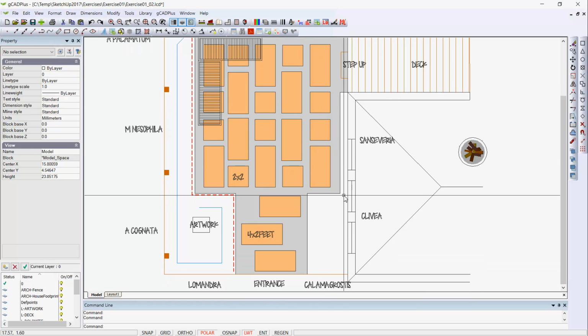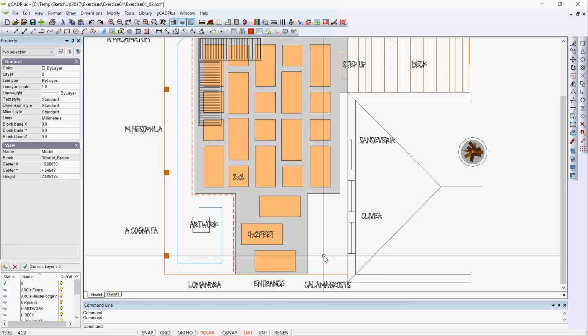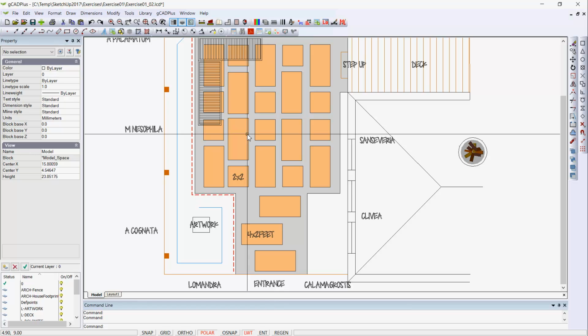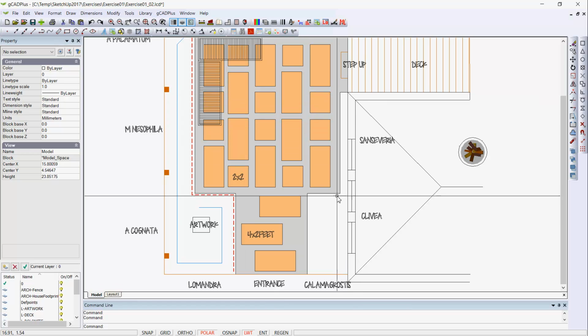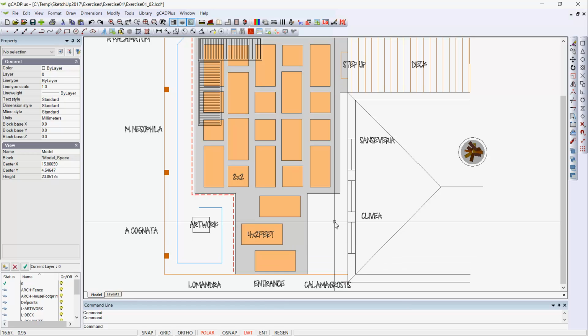So now it's a simple matter to draw a polyline around there, and I suggest you work with, in the properties box, everything on layer 0. Now I can start my polyline, draw a polyline around that zone, hatch it with whatever hatch pattern I want, and that puts some symbology in to